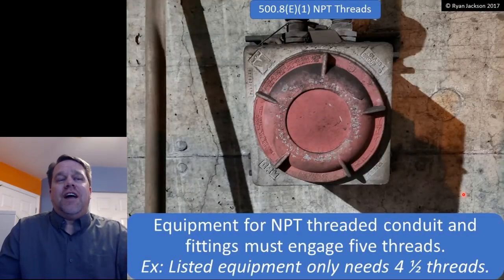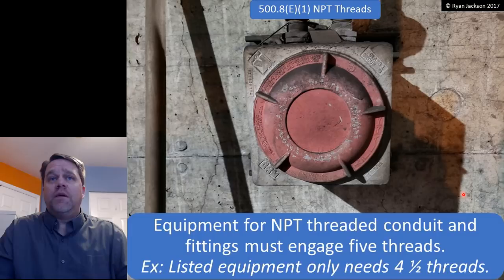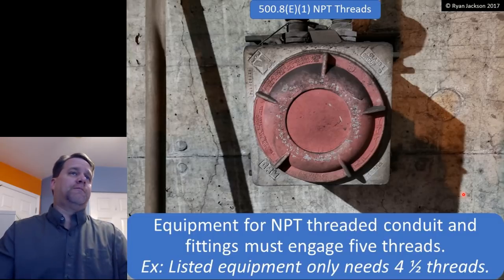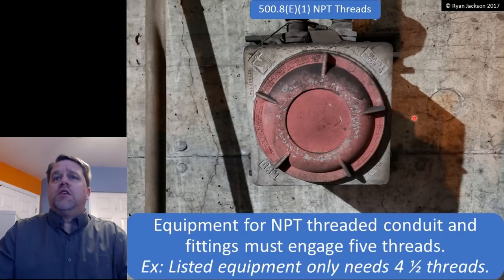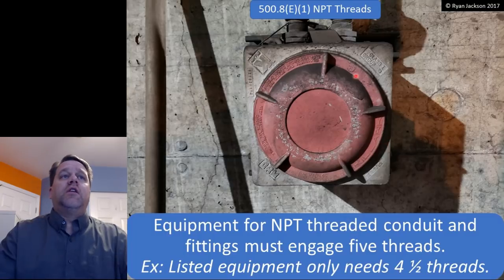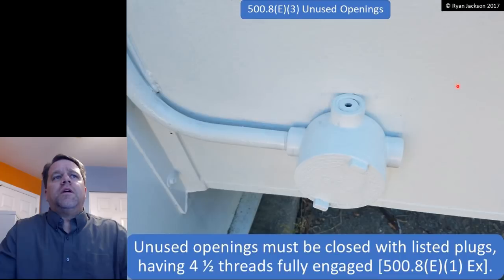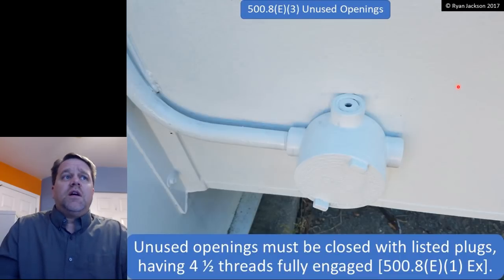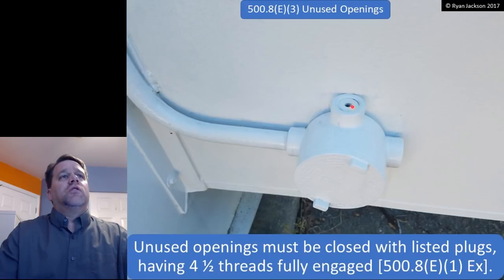Equipment for NPT threaded conduit and fittings must engage 5 threads, but there's an exception. Listed equipment only needs 4.5. So I need to spin this thing in there, make it up wrench tight, and make sure for listed equipment that it gets at least 4.5 threads. For non-listed equipment, at least 5 threads. Unused openings have to be closed with listed plugs, having at least 4.5 threads fully engaged. So we've got to make sure that we've got a listed close-up plug for that unused opening.